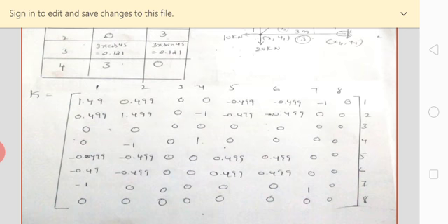AE by L in the matrix of L square, Lm, minus L square, minus Lm; Lm, m square, minus Lm, minus m square; minus L square, minus Lm, L square, Lm; minus Lm, minus m square, Lm, m square. See, this is what is inside the elements of your matrix. And while creating your elemental stiffness matrix for the first element, at the top you have to represent 1 2 3 4, 1 2 3 4.